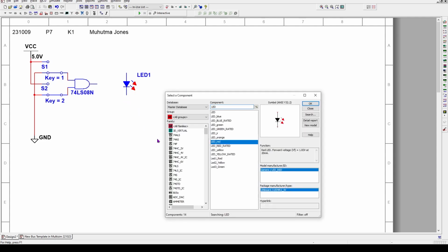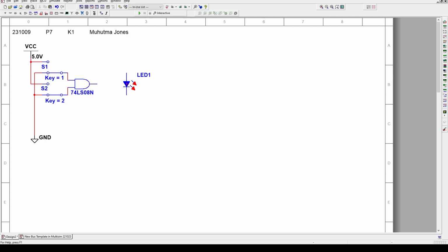That's the schematic symbol for light emitting diode. And I'm putting that in now. And let's close this window for now. So this light emitting diode, I want it, the power, let me say it that way, the power flows through it in the direction of this arrow, but a diode is a one-way switch, and that's what this horizontal line means, it's not going to let the power flow through backwards. Now, later on I'll explain why I didn't want to call that the electron flow, because that is a conventional flow direction, not a true flow direction, but I'll explain that later.